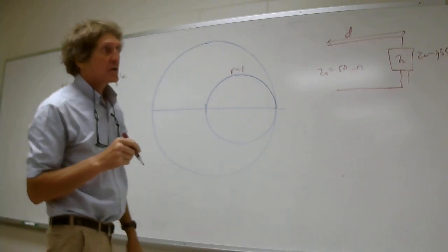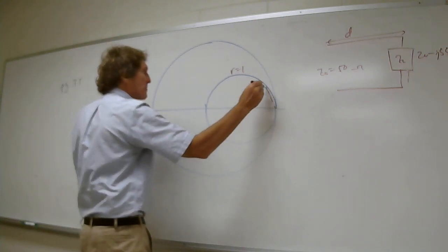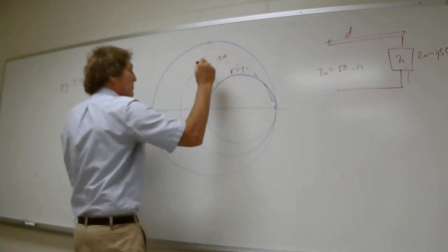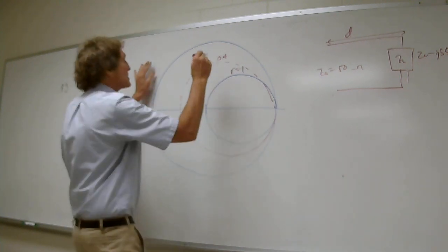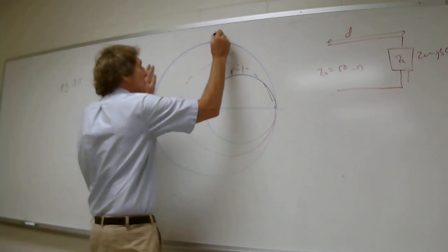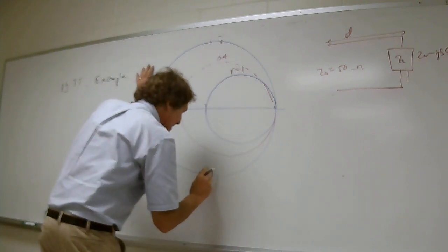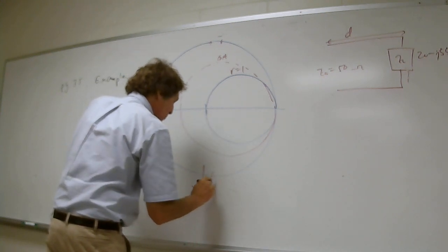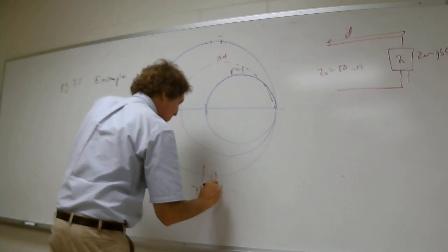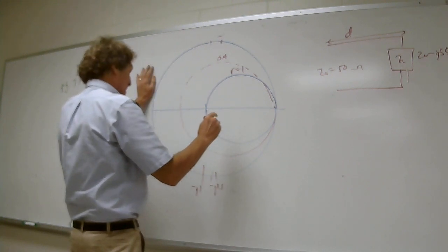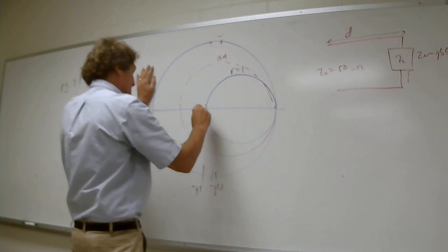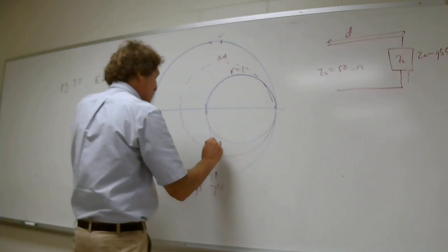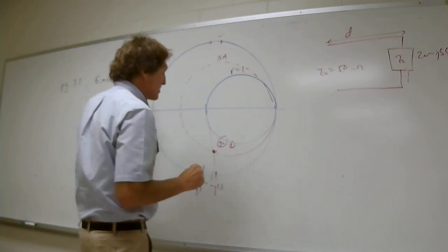Over here, if you get your Smith charts, 0.4 is a circle about this big. This is going to be 0.4 real part. Minus j1.1 is down here. If this is straight down, this is minus j1. 1.1 is about here. You can take a look. And that means the intersection of these two is right about here. I'm just going to call that ZL, and this is my point 1. Can you all see that?